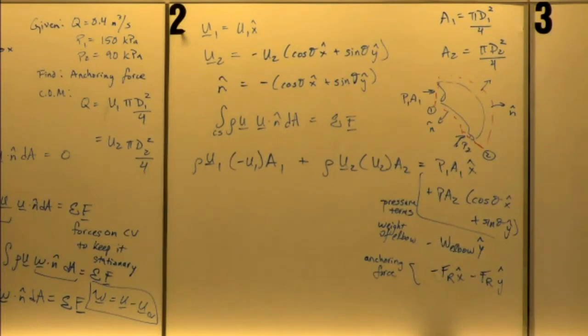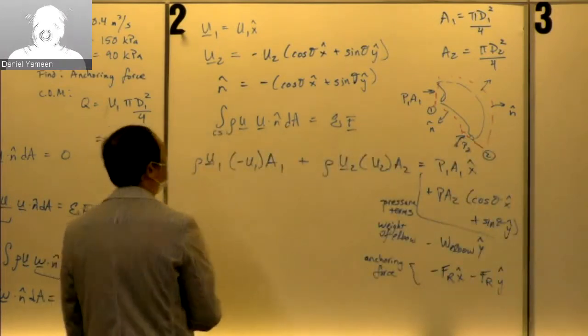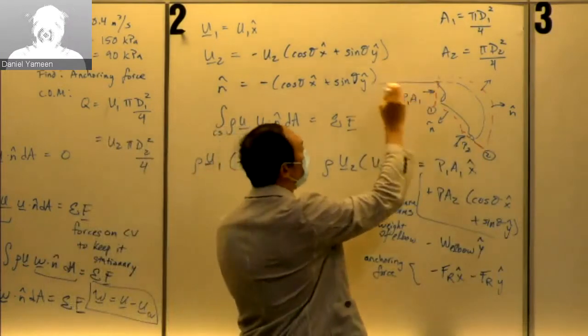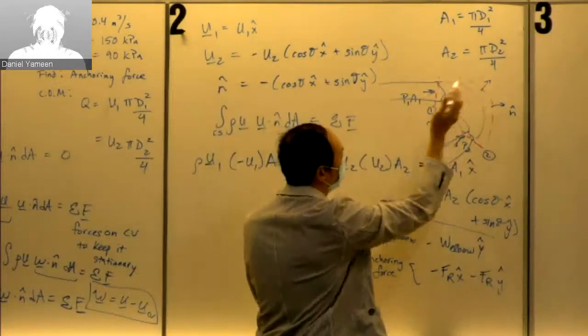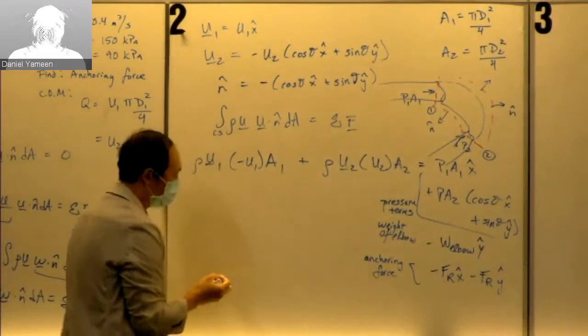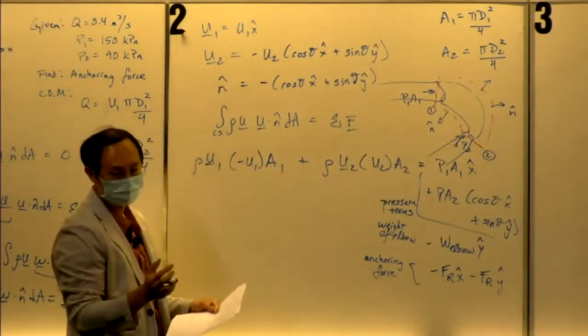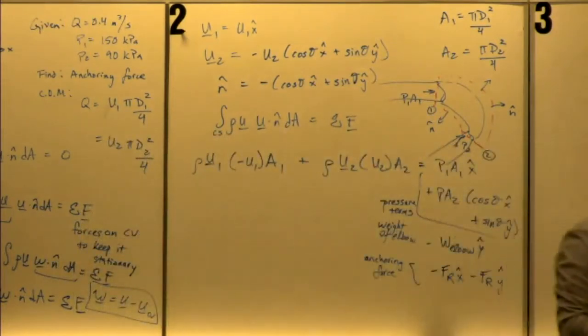How do you know when to incorporate the pressure terms? On some of the homework problems, I would think to include the pressure, but then it depends on the situation. Here, it's like an infinitely long metal pipe, and you're just cutting the pipe off because they're putting the fittings there. In the next problem we do not have the pressure terms, because if there's no pipe enclosing it, there's no way to contain pressures. So let's do that problem now. It's a little more involved because you have to use conservation of mass.